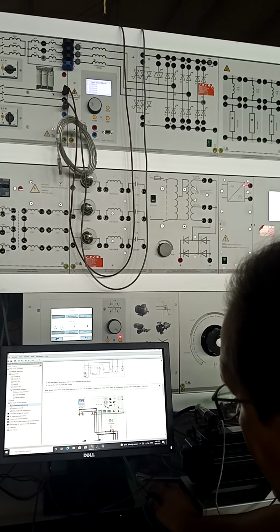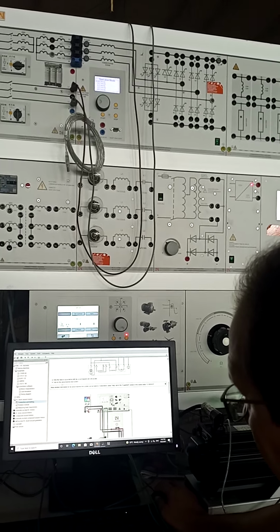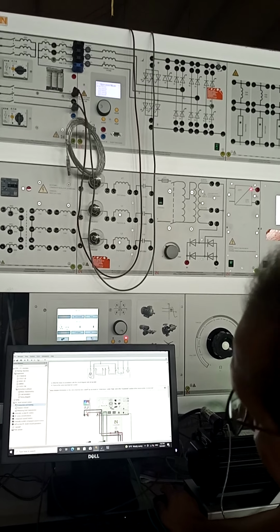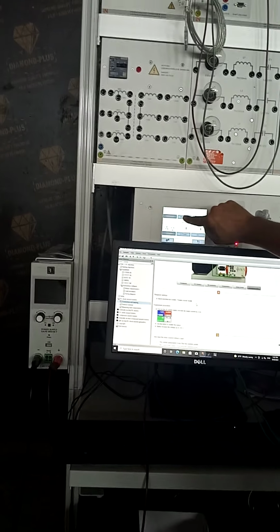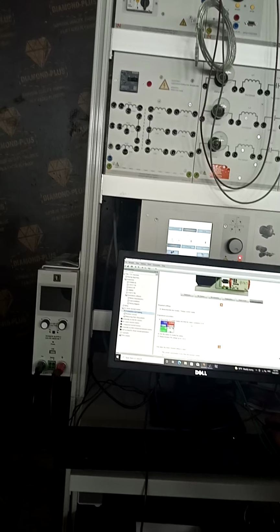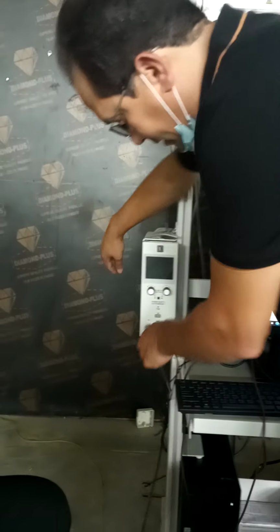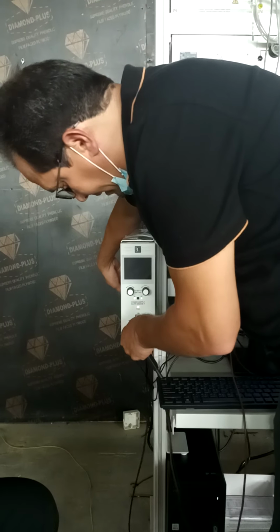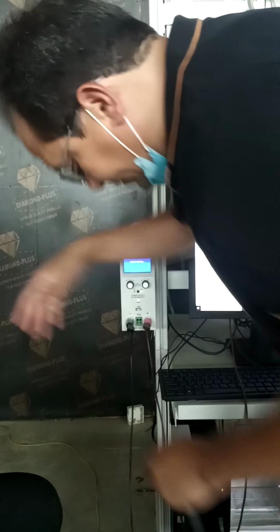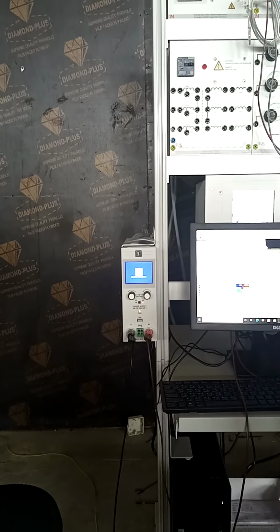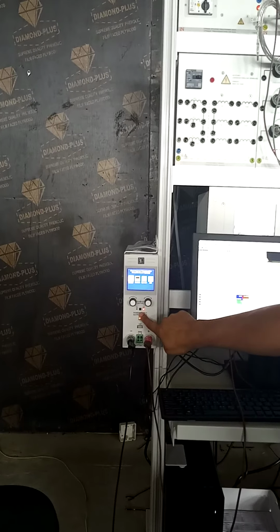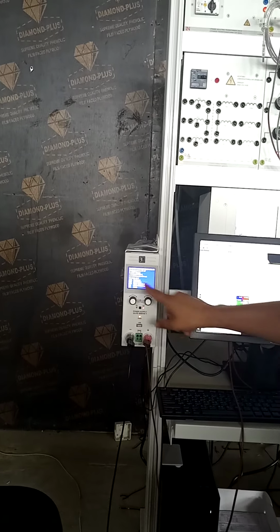Wire the motor in accordance with the diagram. Turn on the servo machine system. Before turning on, I have to adjust something. Required settings: servo machine test system, torque control mode. Then we have the equipment procedure: turn on the DC power supply and limit output to 2.5. This is important. I put this one out. Maybe if I leave it here, it's no problem because the power is not directly out. I need to activate it here. It's more safe.